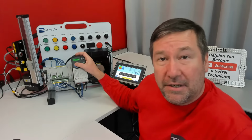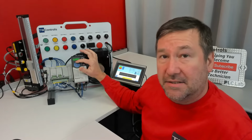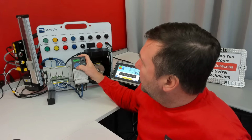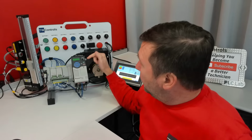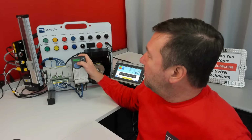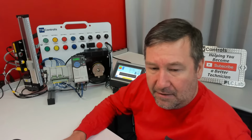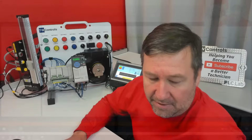And so I'm going to go to P46. So I'm going to hit the select key. The B is flashing. I'm going to hit the up key to go to the P's. And now I'm going to go down to P46. And 1 means operate off these buttons. We're going to take it to 5. That means operate off of Ethernet. And now, if we go over here and we check the box, my motor does start.